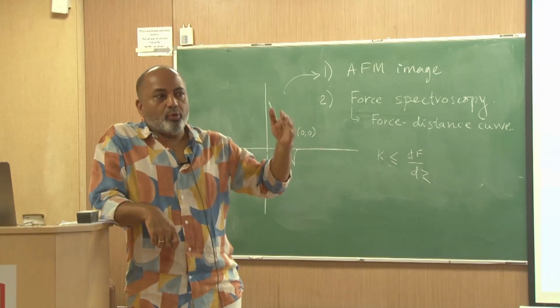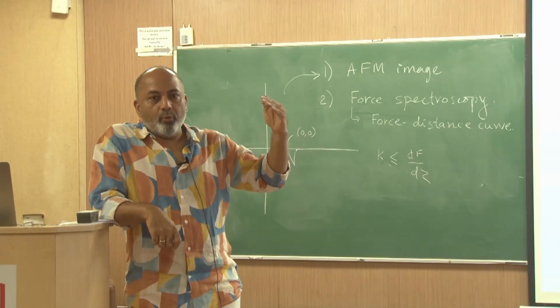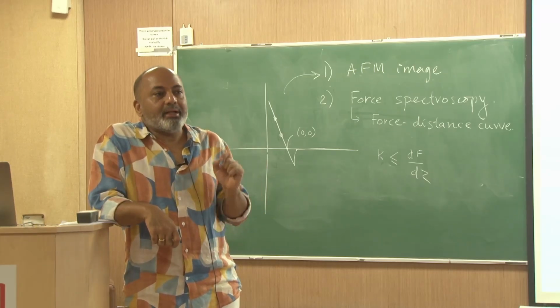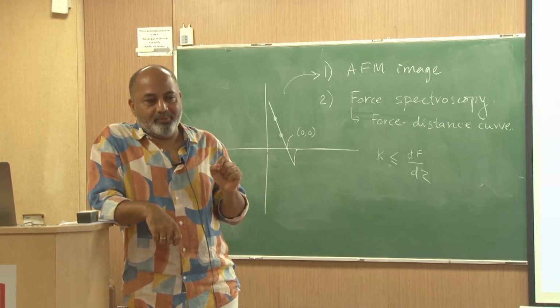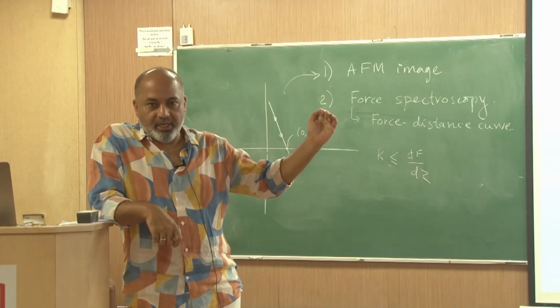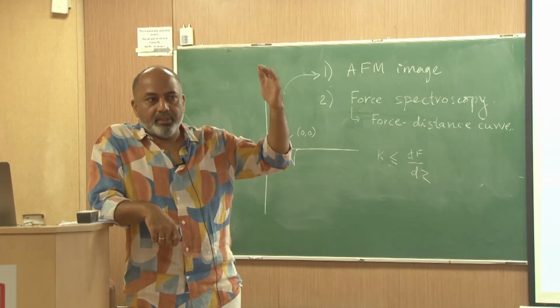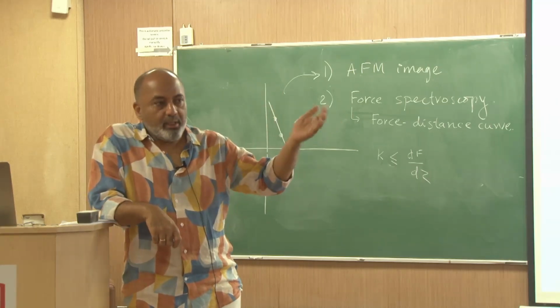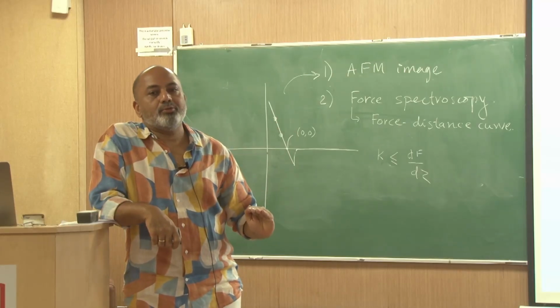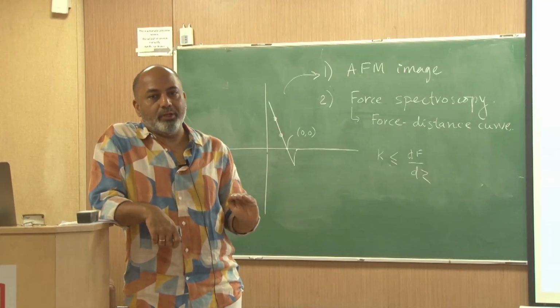It will cool to a point where it drops below 25, and then it stops cooling, but that doesn't happen exactly at 25. There is a room, right? You set 25, but it will go to 30, then you start cooling, it cools down, crosses below 25, comes to maybe 20, and then you stop cooling.